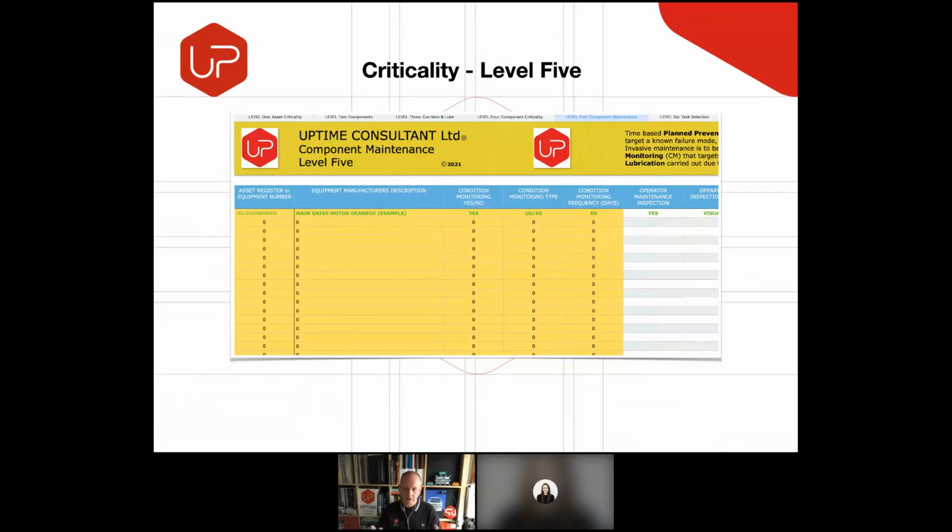An example of that, a place where it only became apparent when doing this, was that the operator group were carrying out temperature measurements for safety reasons once per shift, and they were logging it, and nobody particularly was looking at it. The problem was, when I looked at that, they were using thermography equipment that they'd never been trained how to use, and all the results they were getting from it were false, because they were pointing the thermal imager at stainless steel units and basically taking the temperature of their reflection. So this always reveals these unknowns that I've talked about.